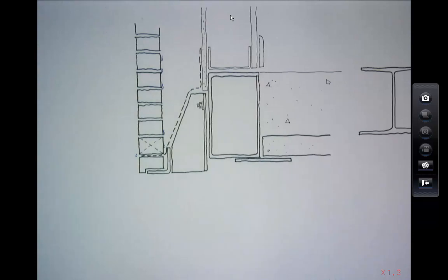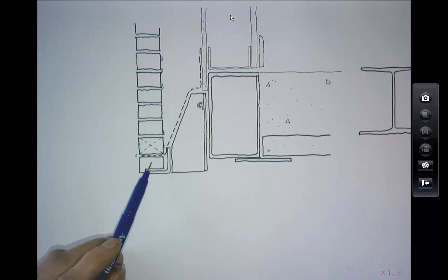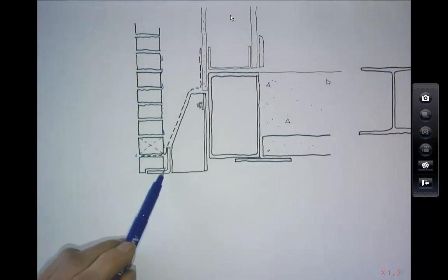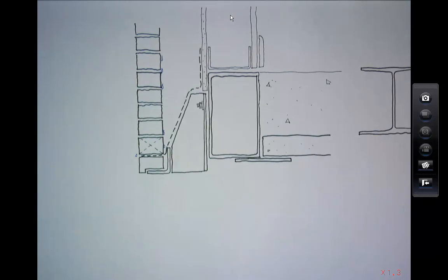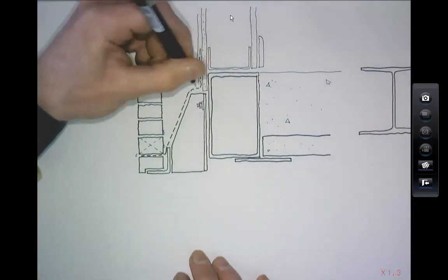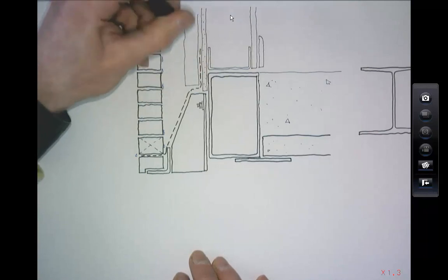Now, you may notice here and say, but you've got one brick that's not protected. So yeah, in theory, if any water got through that one brick, it's not getting evacuated by your weep hole, but in practice it doesn't really happen. So we've got that. What else do we need? We need our insulation, like this.